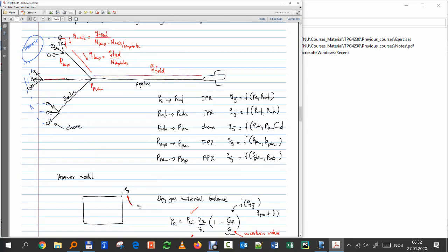And I told you we are going to make it like an energy balance, but we have one big issue, and I'm going to make some comments today about the choke. The choke model we decided simply to neglect. So that's where I'm going to make my equilibrium point. I'm going to calculate energy or pressure all the way upstream of the choke, and energy or pressure just downstream of the choke. Then I have to compare these two values of pressure, because I have the choke in between.